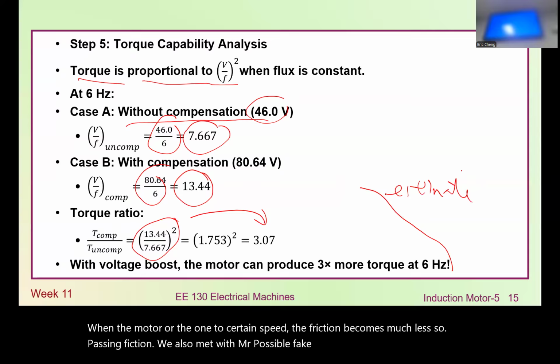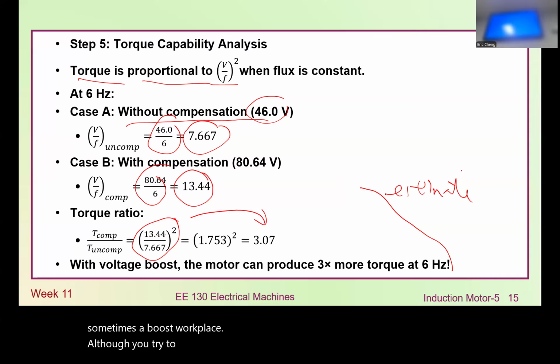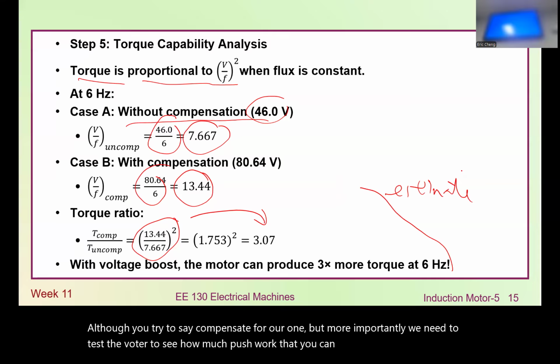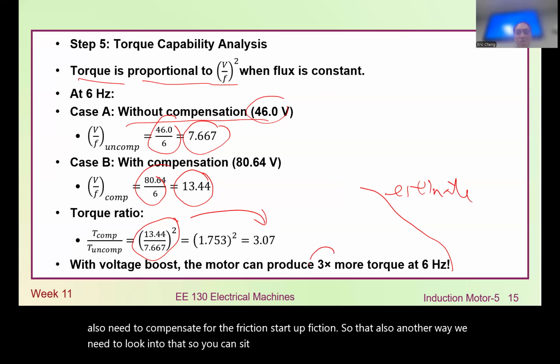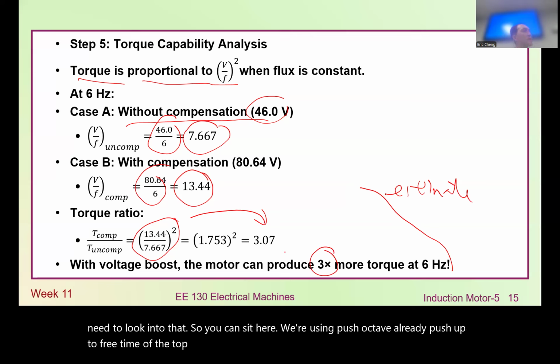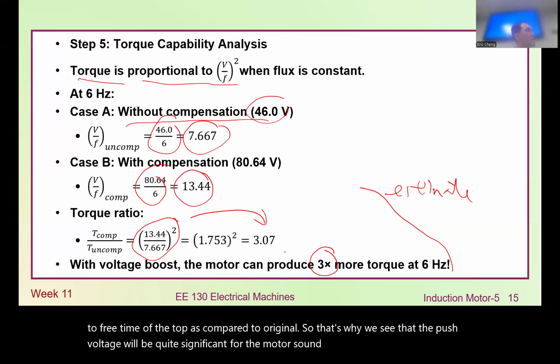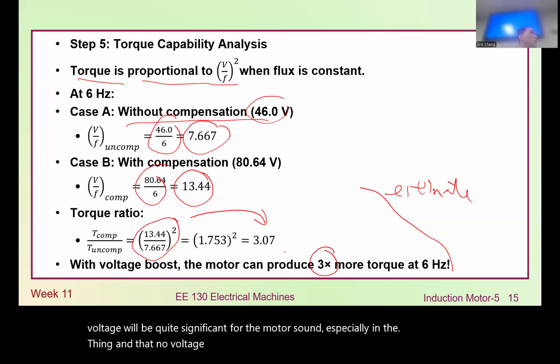So sometimes the boost voltage, although we say it compensates for R1, more importantly we need to test the motor to see how much boost voltage we need to start. So this boost torque also needs to compensate for the starting friction. That's another way we need to look into that. You can see here, using boost voltage we already boost up to 3 times the torque compared to the original. That's why the boost voltage is quite significant for motor start, especially in the starting and low voltage or low frequency operation.